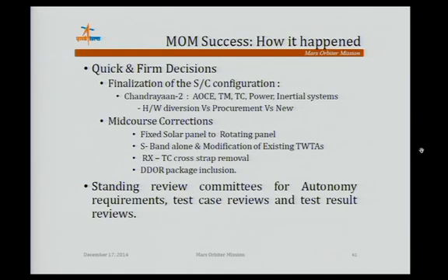They were basically thinking of a fixed solar panel, but finally, if you see the angle required for motion throughout from Mars launch to Mars arrival, that angle was very minimum, within some plus or minus 40 degrees only for the solar panel. Therefore, a simple rotational mechanism where offsetting can be done to achieve the power generation was decided, with a simple stepper motor put in, so that depending upon the phase you can command the spacecraft automatically to take the data from EEPROM and use it for the pointing of the solar panel correction required throughout the phase.